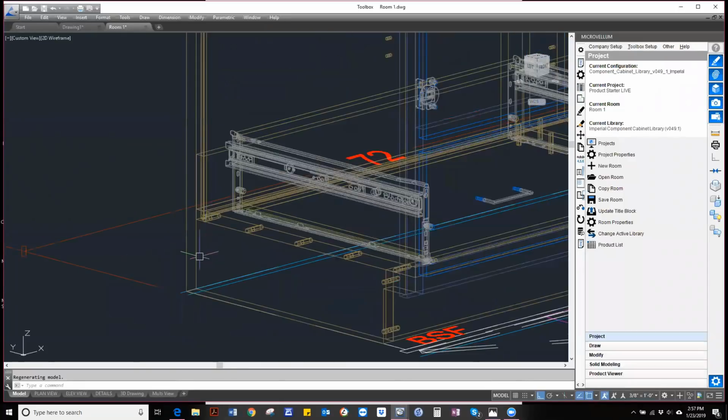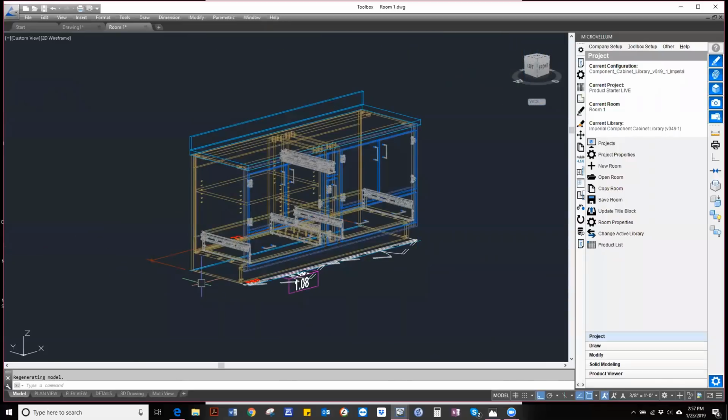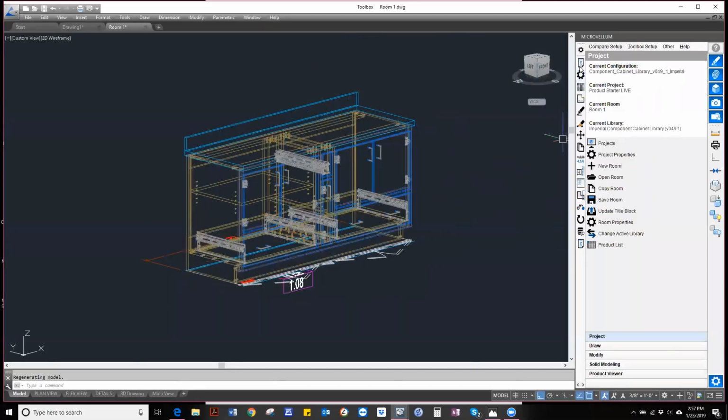And because it's based on that base left side material, and then it looks at the material type, and then that thickness, and then calculates it from there, all of that math is pre-built inside of there. So even if you change it 1/100th of an inch, or from a 3/4 to a 1 inch material, it's going to be able to modify that.